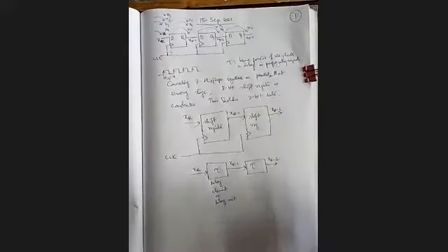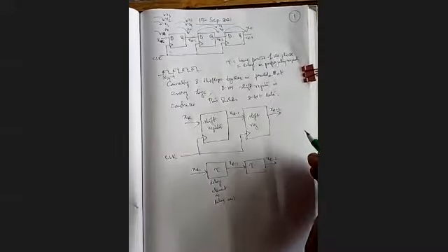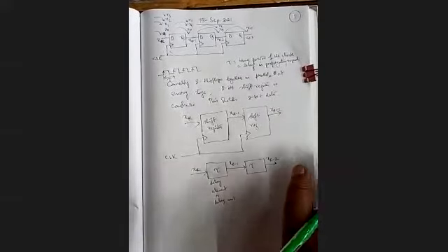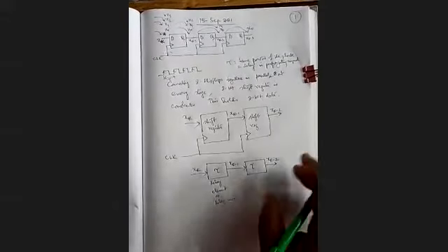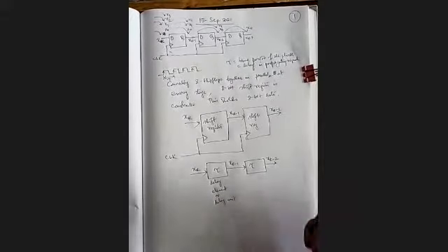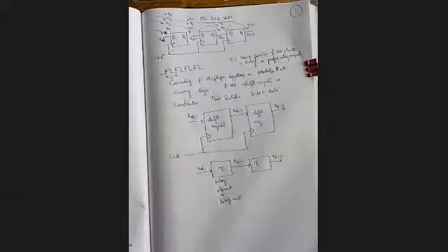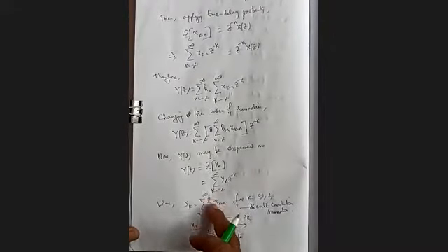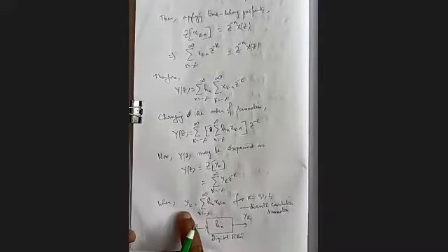Basically, each tau is practically nothing but a shift register. Clear? So when we get various samples that are stored at every stage of the shift register, we can multiply them with the corresponding values of H, and they will be added to get our particular output YK.